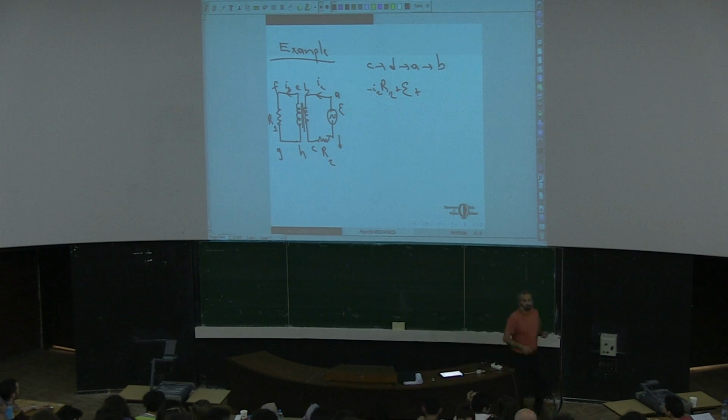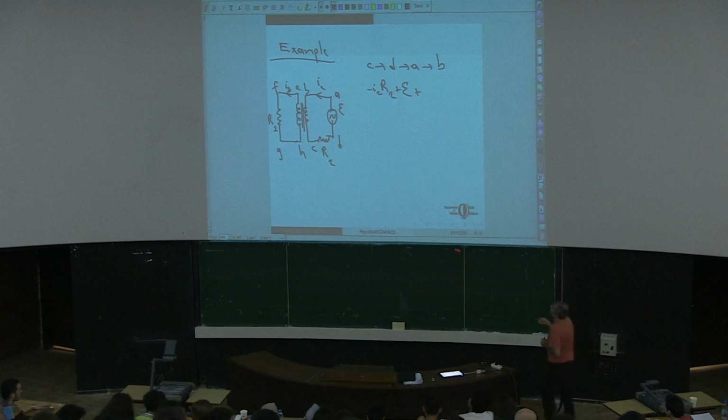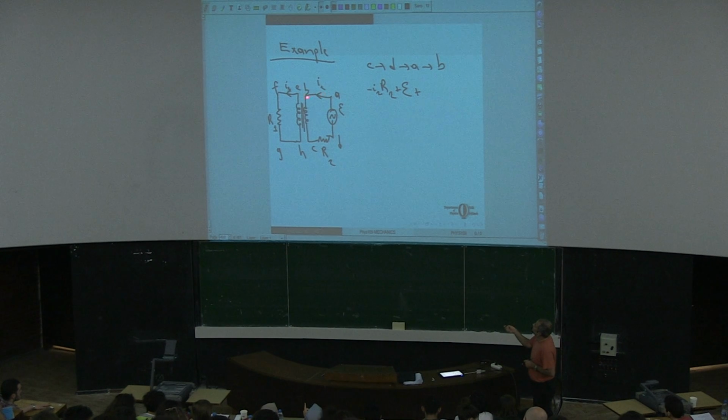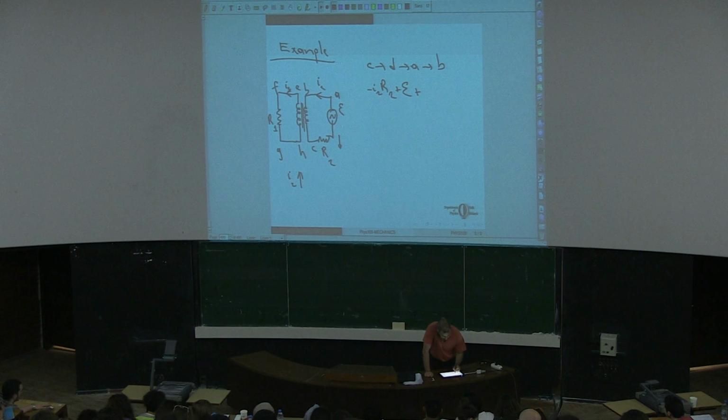Now that is a self-inductor. Now let's say I2 is increasing. If I2 is increasing, it will try to run a current in the opposite direction. So this will behave like the positive terminal, this will behave like the negative terminal.